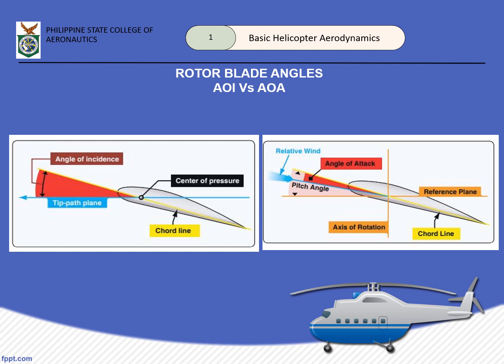So in the absence of induced flow, angle of attack, and take note of this ha. Kapag wala tayong induced flow, angle of attack and angle of incidence are pretty much the same. So a change in the angle of incidence changes the angle of attack, which changes the coefficient of lift, thereby changing the lift itself.